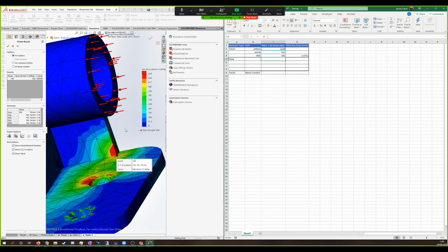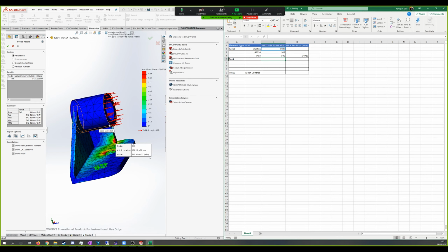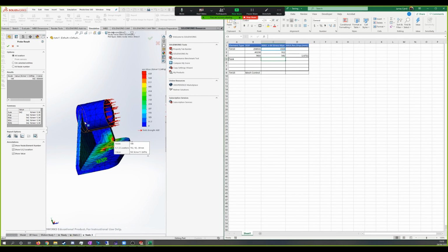What are you noticing there, James? It gets shit when it's low polygon. Yeah, but what's shit? The accuracy of the result. Yeah. Think about the trend that's happening. Oh, it's decreasing. Yeah, well now, so increase your degrees of freedom.